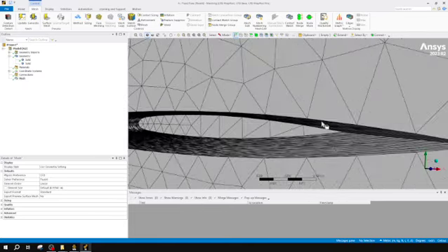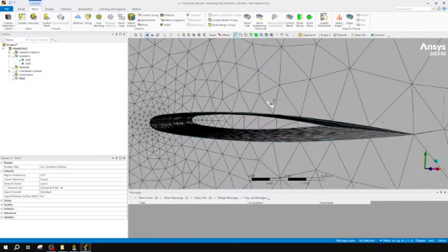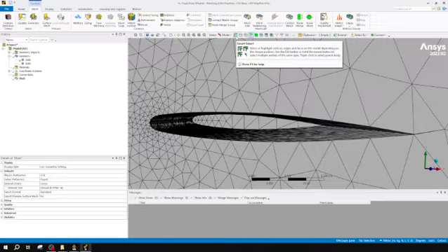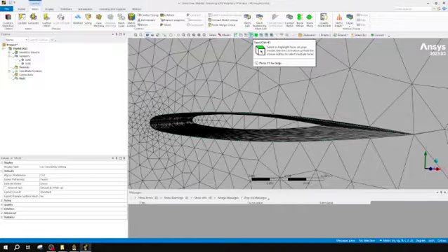So now that I have the default, I'm going to want to go ahead and refine some different things. First, this is not an acceptable mesh size for my wing's surface. So I'm going to want to start by actually defining my wing. To do that, I'm first going to change it to select my faces. It has this smart select where it'll try and select what it thinks you need, but I much prefer defining what I actually want to select. And for this, I'm only going to be selecting faces.